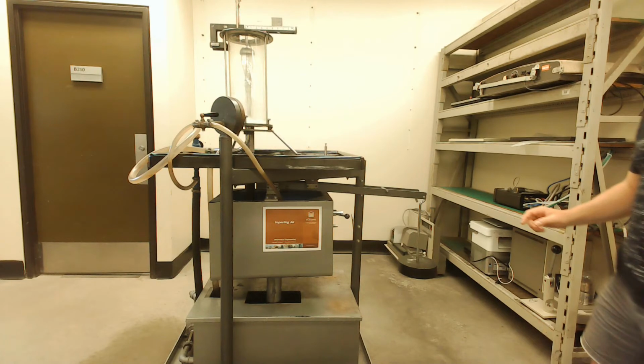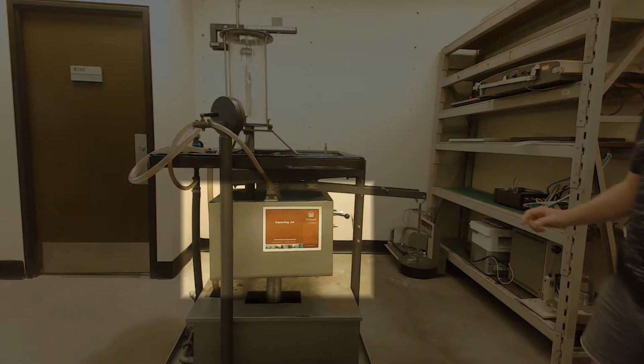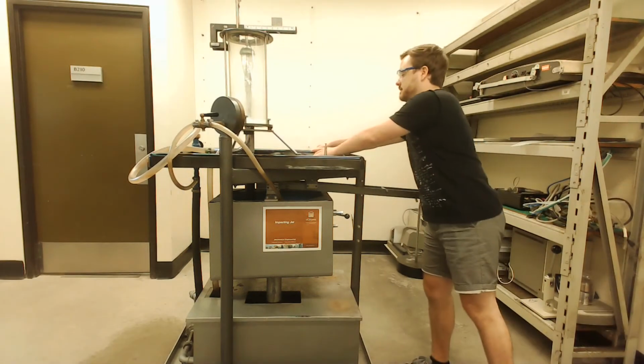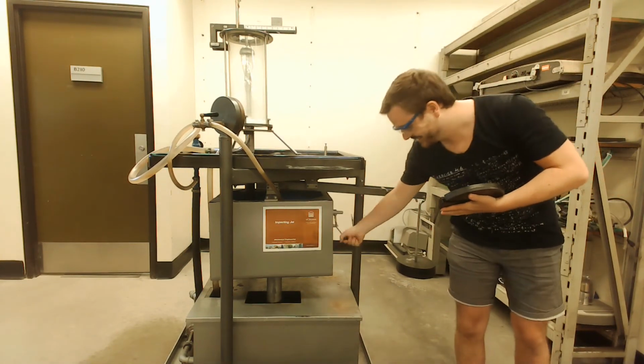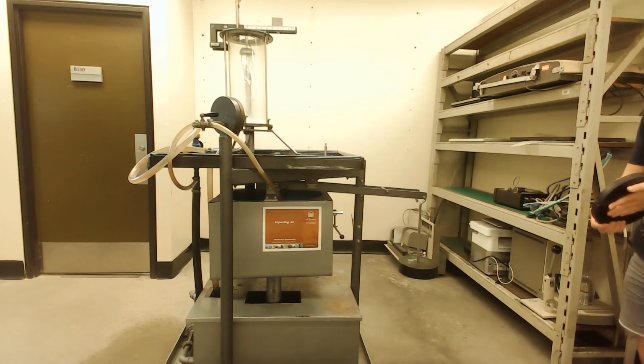The final step is to determine the mass flow rate of the system. This is done by another balance tank located at the bottom of the rig. A lever is initially flipped in order to let the tank collect a certain amount of water. Once the tank has collected sufficient water, the balance will tip.